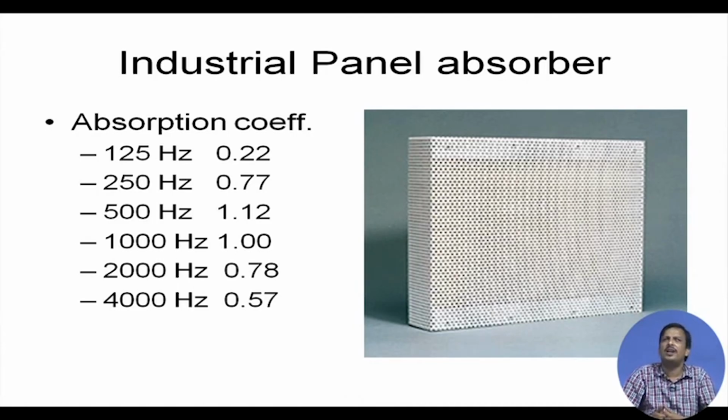If it is only a lecture theatre like a classroom, then the reverberation time requirement will be different, and the acoustic treatment will be different. So, in the next class we will discuss how to design auditorium acoustics, or which part of an auditorium should be treated with which kind of material and why.